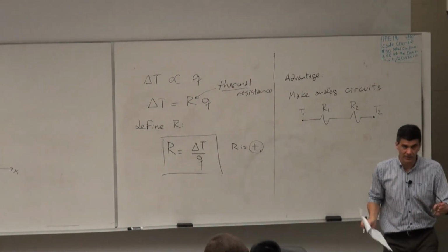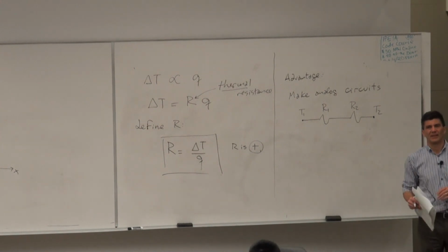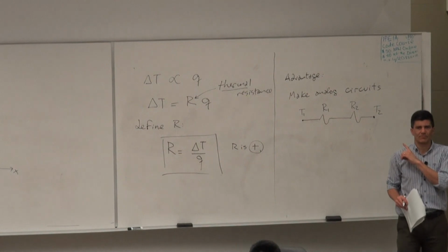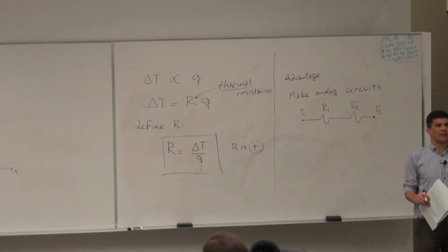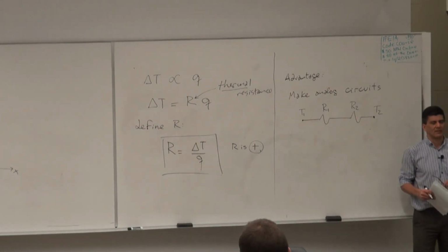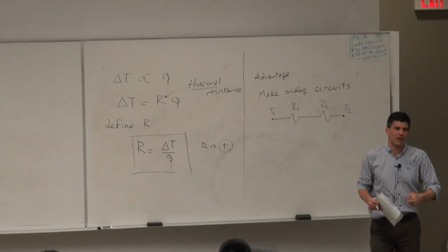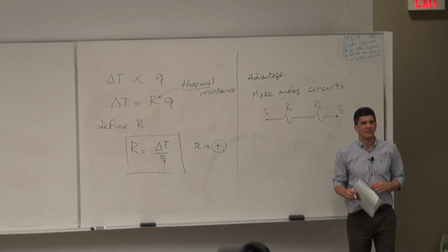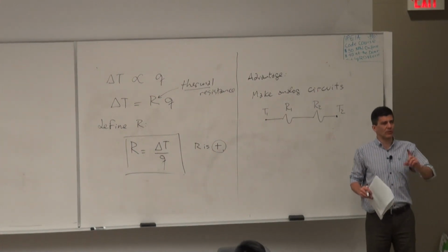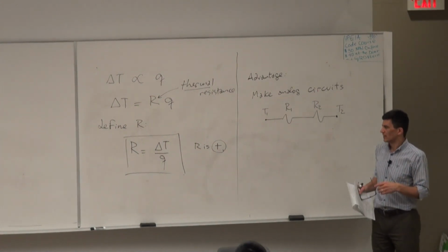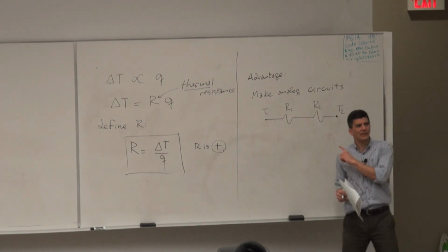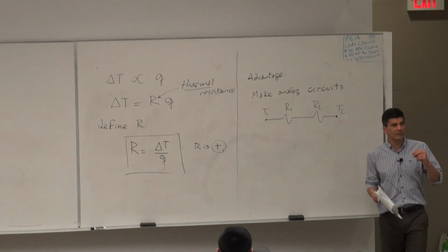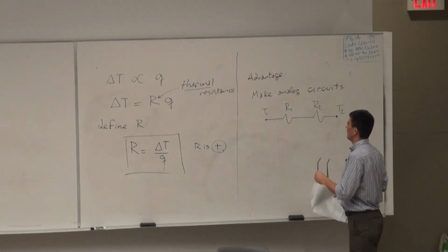We're going to spend the whole next week seeing cases like this. You know what this is? This is a heat exchanger. Actually, in a heat exchanger, you have many more resistors than this. You have fouling, you have convection, you have conduction, you have fouling again, you have convection on the other side, right? And if you were to do it by brute force, you die. But if you do it like this, very quickly, you have an answer that is of practical value.